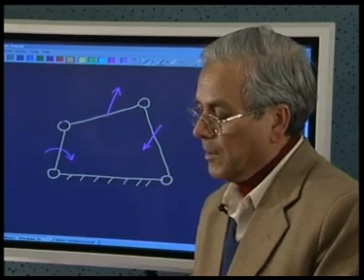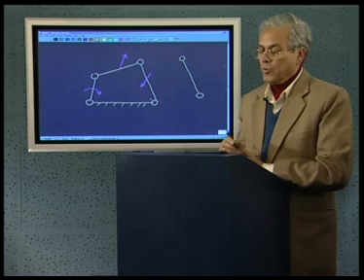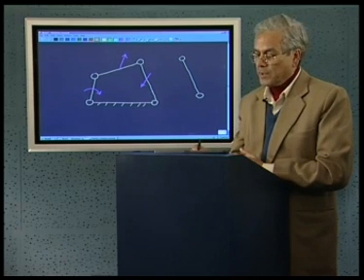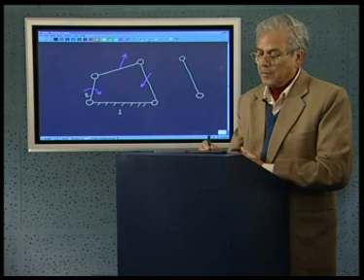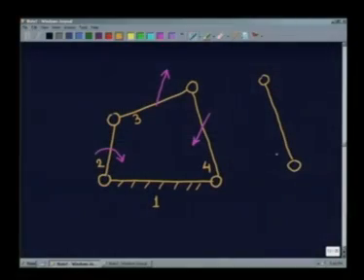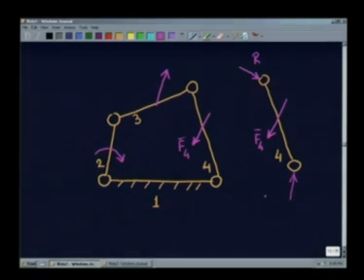That means this link, which in your terminology you have termed as link 4, the fourth link, is subjected to this external force, we call it say F4, and there will be 2 hinge forces, reaction forces, one reaction force from here, another reaction force here, we call it R14, and this I call R34.